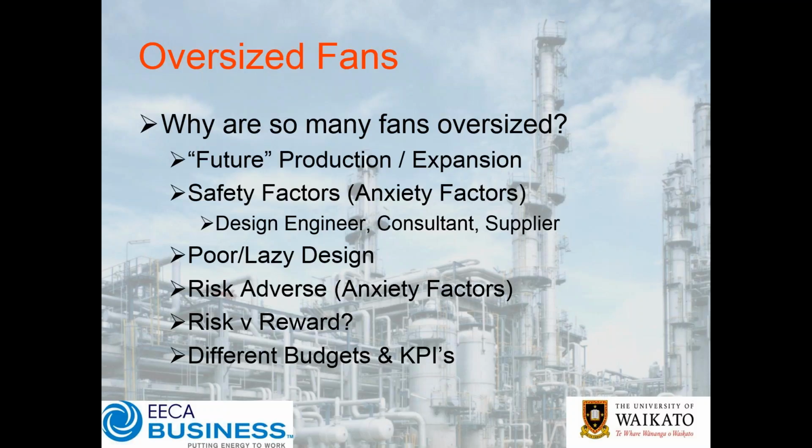And as we do that, of course, the other thing is you might not have done a lot of detailed design to know precisely what your pressure drops are going to be, and so the lazy or poor design approach there would be to just make sure we've got plenty of headroom. We don't want to be short of pressure. We want to have a bit extra flow, and so we overcompensate.